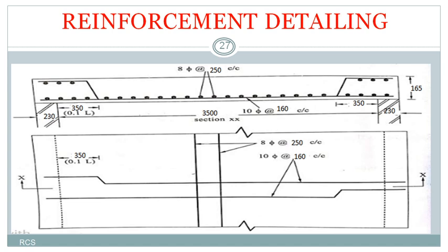After obtaining all these values, let us see what reinforcement detailing is. We have designed a simply supported slab. That means this slab is supported over two supports, or two walls, and the clear span between the supports is 3500 mm, that is LX. We are assuming a 10 mm bar, and the 10 mm bar can be used at a spacing of 160 mm center to center. This horizontal black line is the main reinforcement in the shorter direction, with a 10 mm diameter bar at 160 mm center to center.